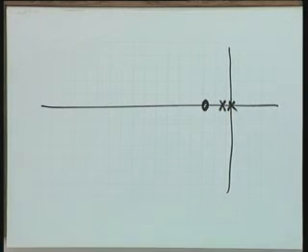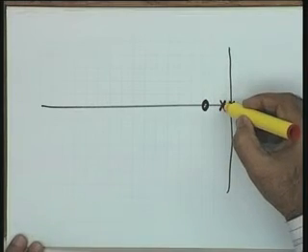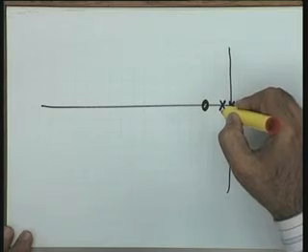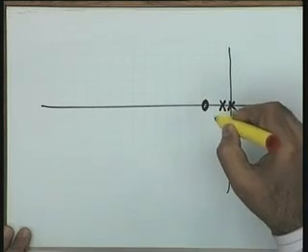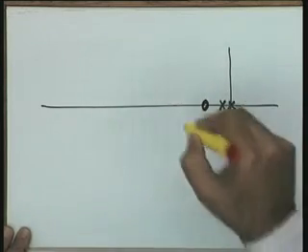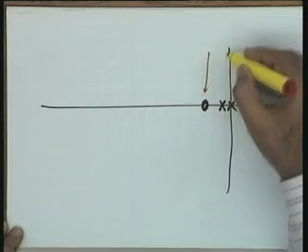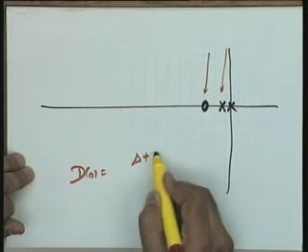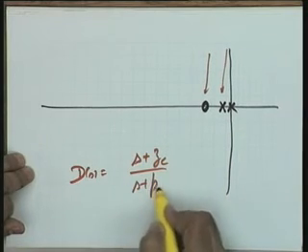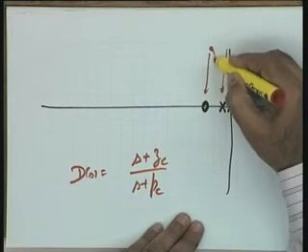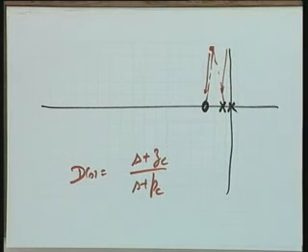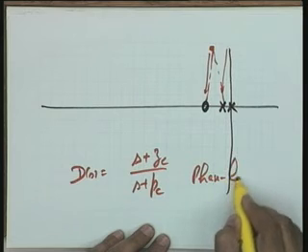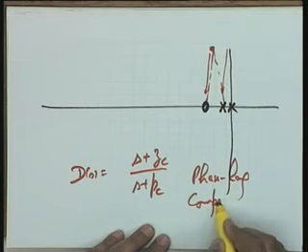You see, these are the compensator poles and zeros. The compensator pole, instead of making it at the 0, I am placing it close to 0. You see this point, please. The compensator pole, instead of fixing it at the 0, I am placing it close to 0, and this is your compensator 0. And therefore, D(s) becomes equal to (s + zc)/(s + pc). Can you tell me what is the net angle contribution? Is it positive or negative? It is negative, and because of this, this type of compensator is called a phase lag compensator.